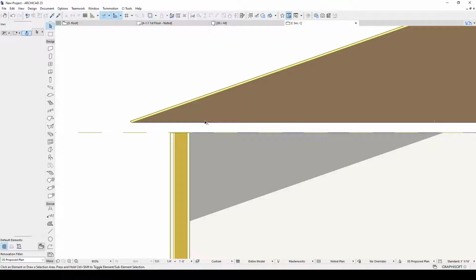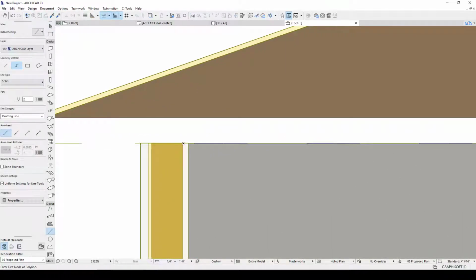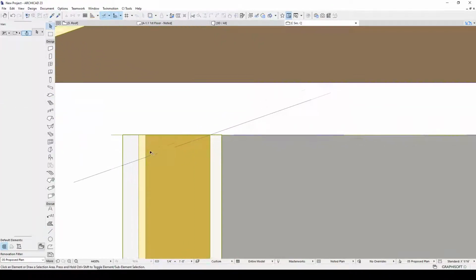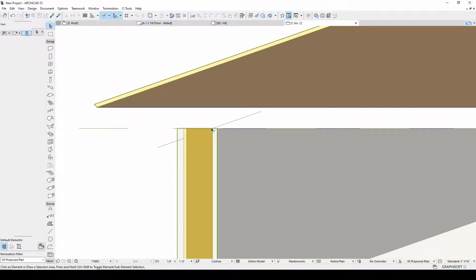One thing to consider, and I'll just trace it here. If I have the rafter coming through, we have a bird's mouth here. So the rafter comes in down. The pivot point wants to be the inside face of stud when I'm doing a conventionally framed roof.